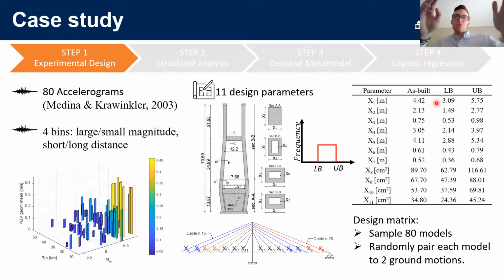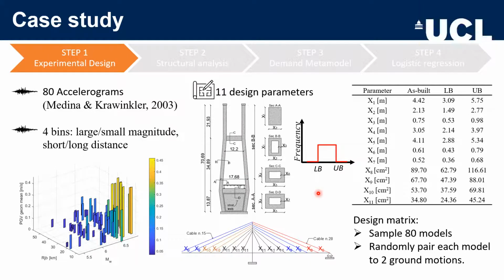Then of course you have to make all the checks to guarantee that this variation is reasonable. For example, you might have to check the buckling load in the pylons, or any other condition that might not be verified under different loads. All right, thank you. Thanks.